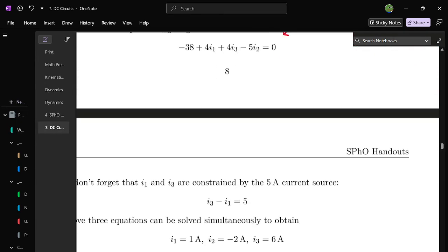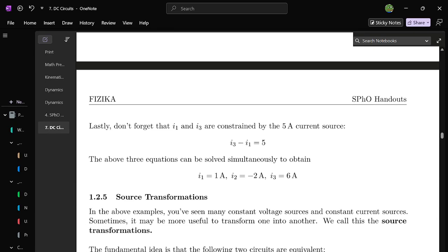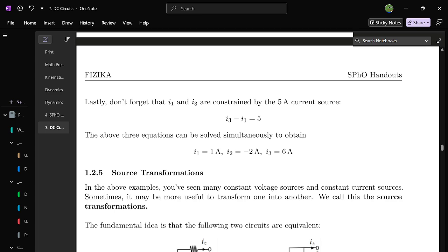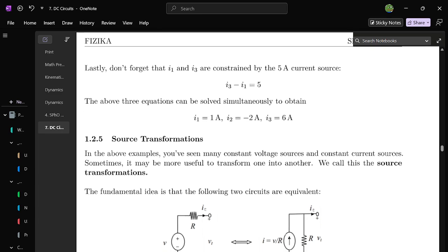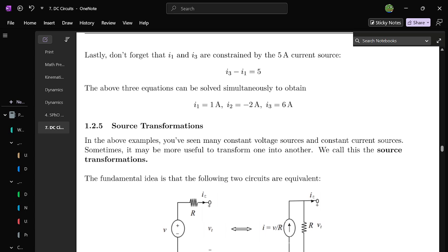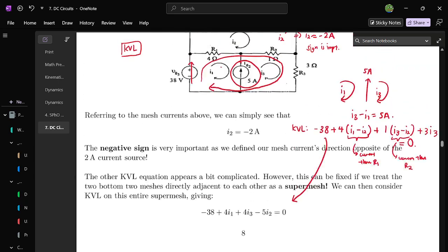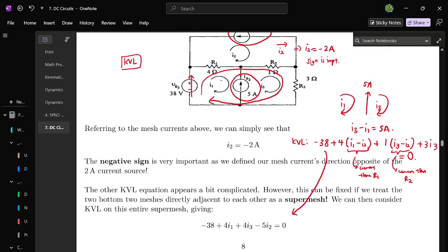And once again, it becomes a thing of solving simultaneous equations. So both nodal analysis and mesh analysis eventually reduce to simultaneous equations. And that's kind of an elegant thing as compared to bashing out Ohm's law for everything and keeping track of all the potential differences. I think it's much easier to just bash out simultaneous equations at the end. Okay, so there's much more practice for both nodal and mesh analysis in the problem set. We can go through some problems later if time permits.